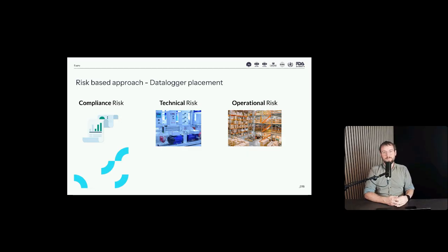Secondly, we have technical risks, and we've been through a lot of those. Those are things like radiators or HVAC systems. Where is the air coming from? Where does it radiate? Doors, gates, the forklift chargers, windows, insulation, that sort of stuff. Those are all risks associated with how the building is built, or the cold room, or the fridge or freezer is built, just inherently in the way the design is. And then lastly, we have operational risks. Those are some of the risks that we've talked about with equalizing product temperature, or opening and closing doors and gates, power failures, people entering and leaving, and so forth.